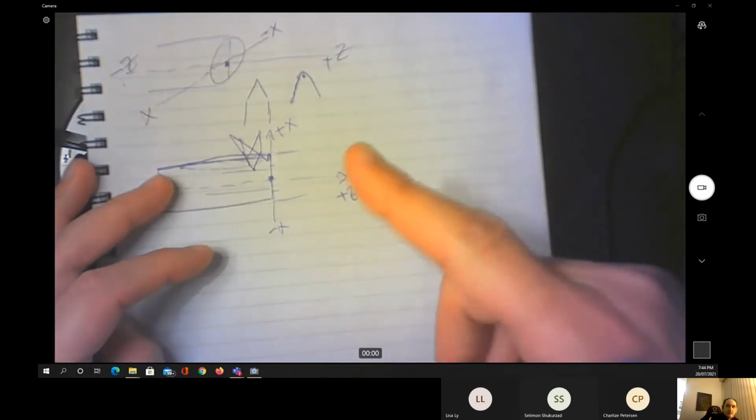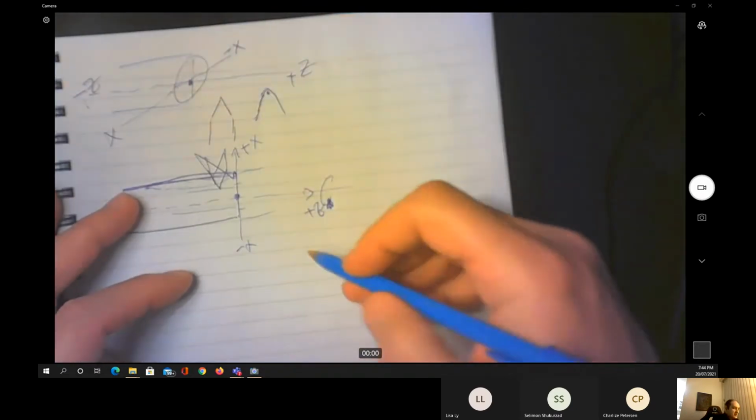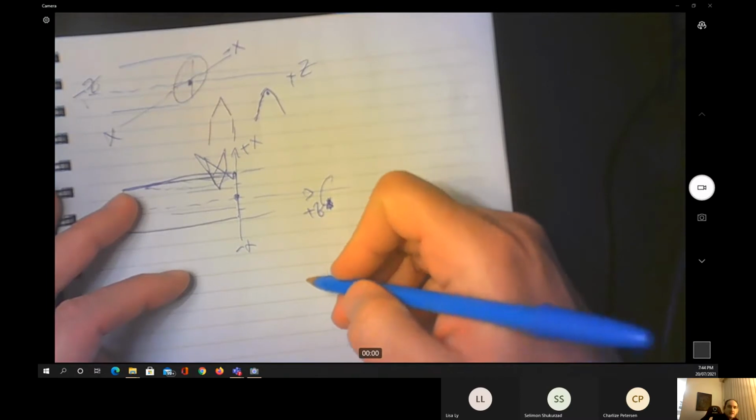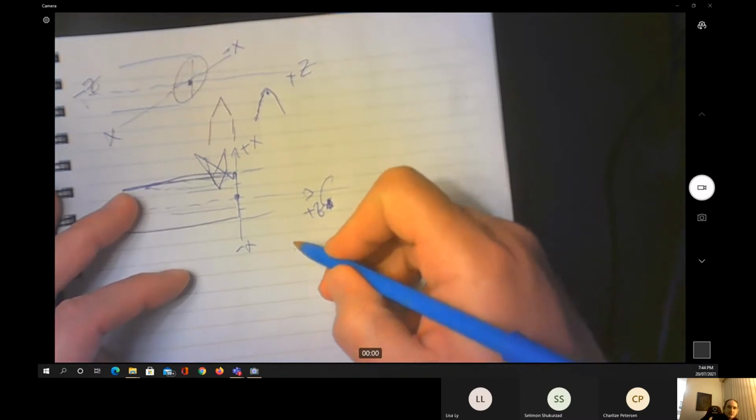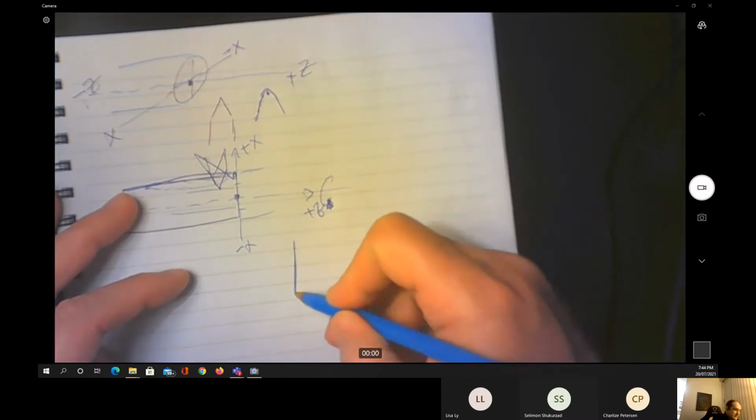When you insert the code to the machine, you can mention that the radius is equal to, for example, 0.02 millimeters or 0.2 millimeters, and the machine will do the offsetting automatically, changing the whole code or just pushing the thing and making this compensation. The other thing we have for the turning operation is, you remember something in the turning machine is called the tool post.